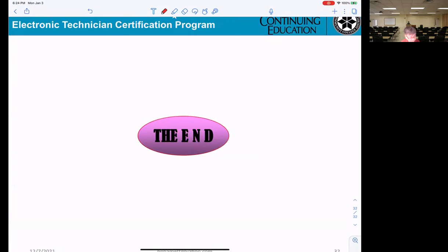And also, I want to make sure you still memorize this, okay? Bipolar means the current controlled device. JFET is a voltage controlled device. The difference between the JFET and bipolar: JFET has a very high input impedance, but it doesn't have a very high gain.